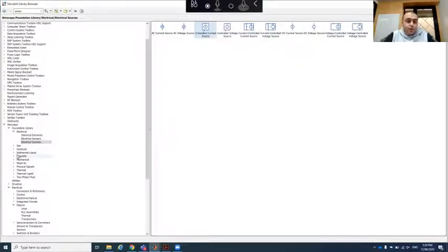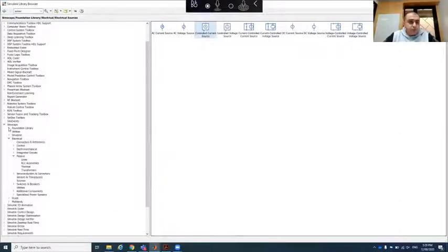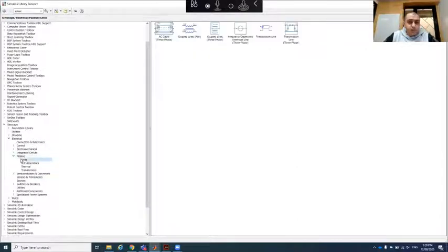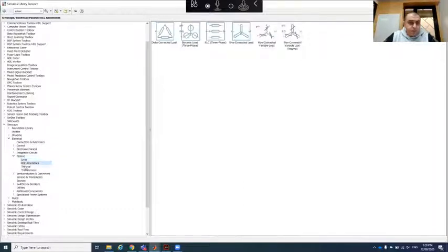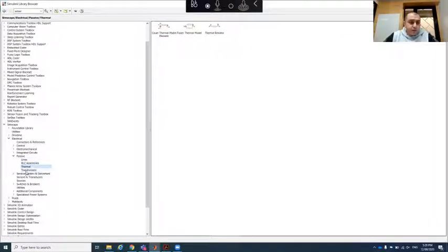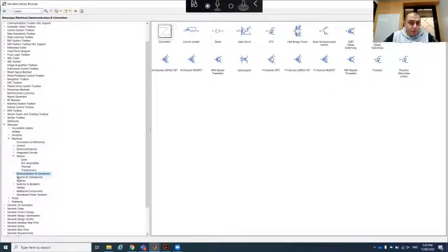Okay. Then after that, I need to have a diode. So again, in Simulink, I just have a look inside the library, for example in the passive components. Then I need to find where the component is. So here, if you can see, I can find the diode right here, just add it to the circuit.